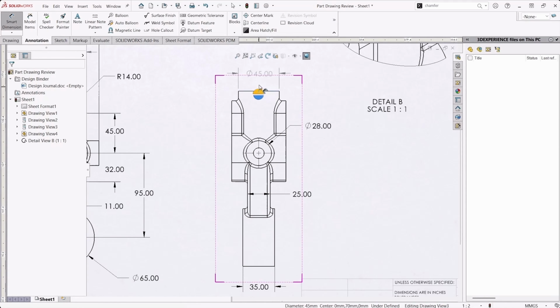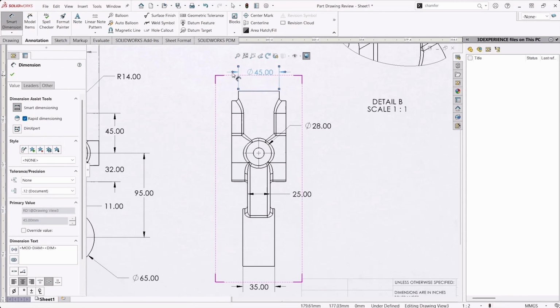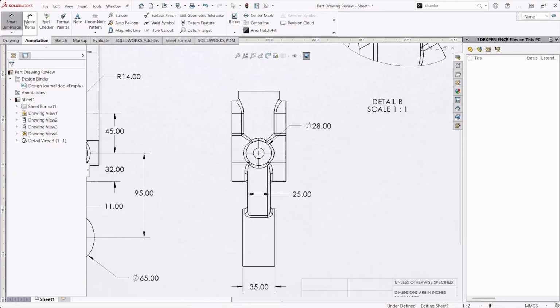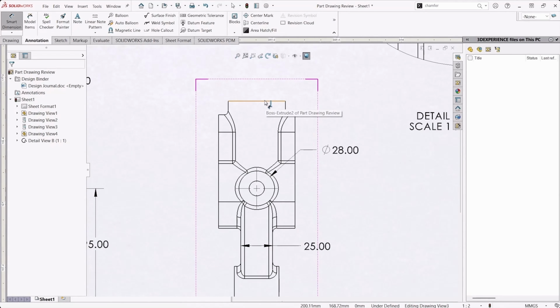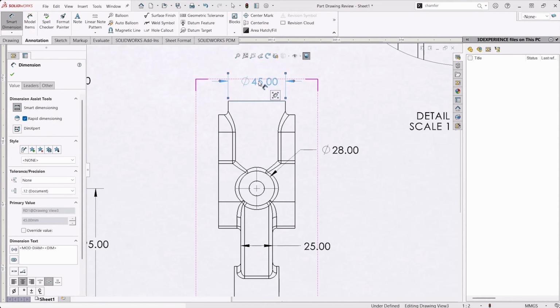Then beyond that, we've got the dimension palette. So when I place this dimension down, note that I have a window that pops up. And when you move your mouse away, it likes to disappear on you. But there's another way that we can access that. If I put this dimension down and I don't move my mouse, I get that little pop-up button. I drag my mouse to it, I get this dimension palette. I can do a ton of stuff within here. But if I need to reference it again, if I just click on that dimension, it'll re-highlight over here.